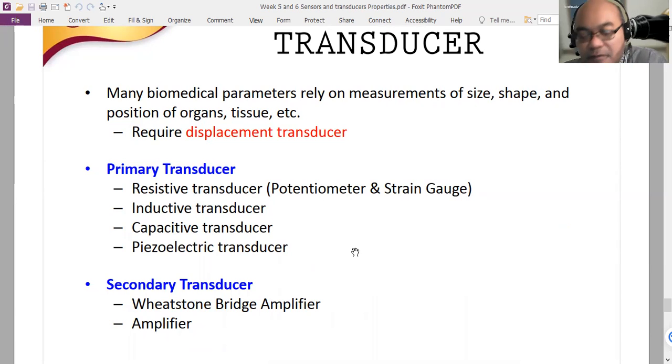Then when we work with digital, we first convert that analog domain voltage into the digital domain, in the form of digital binary number bits to represent the information. So in order to do that, we have to convert the resistance change into voltage change. We can use a Wheatstone bridge and also an amplifier. Okay, so what is a Wheatstone bridge?